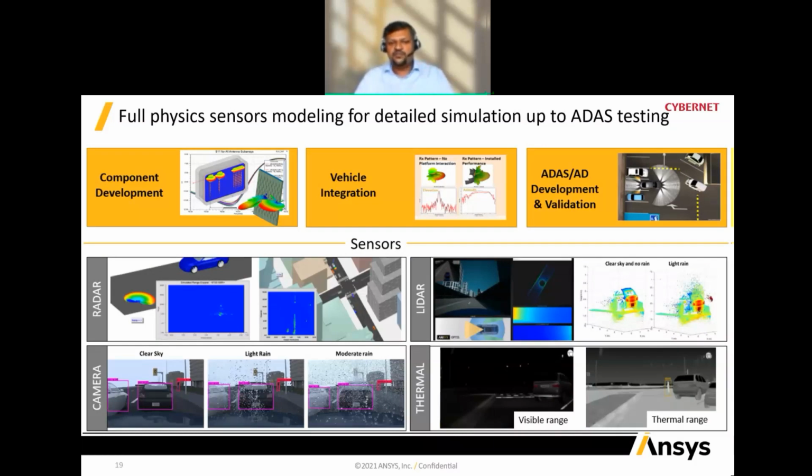and see what kind of field of view it could have, what kind of noise it creates, or what would be the distortion, vignetting. So the different challenges with the camera. The same way with the radar or lidar, with cross communication, with the energy loss. So we can look at different challenges altogether, and then work on the vehicle integration, bringing these sensors, mounting on